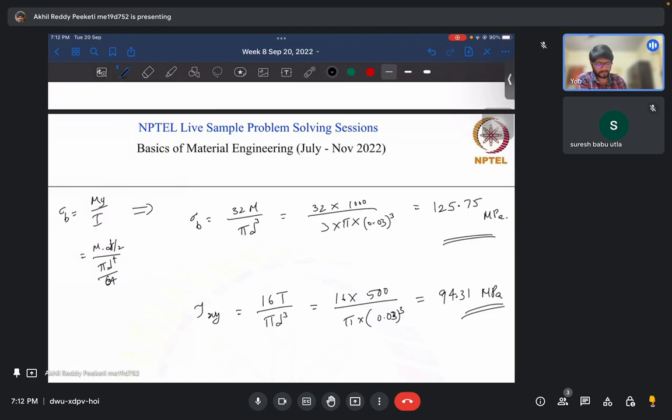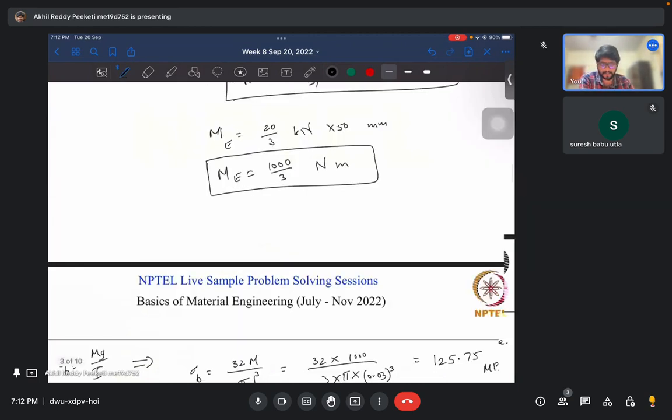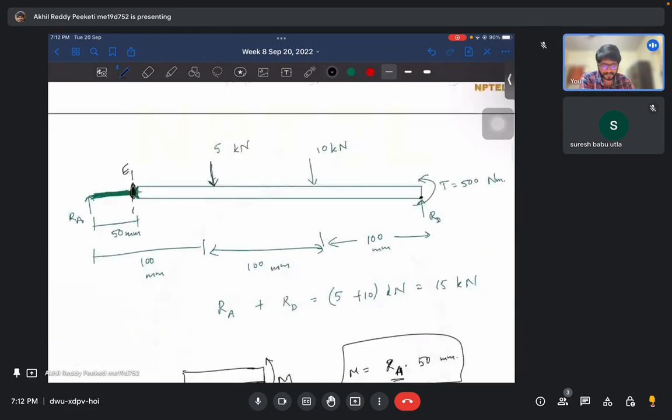Now one thing we need to understand clearly is these forces are acting only from the top. So when the shaft is rotating, the point of the force with respect to a point on the shaft keeps on rotating. So this comes out to be an amplitude or alternating stress.